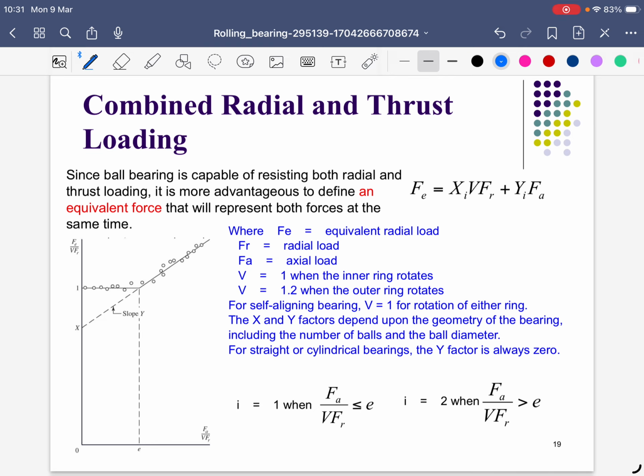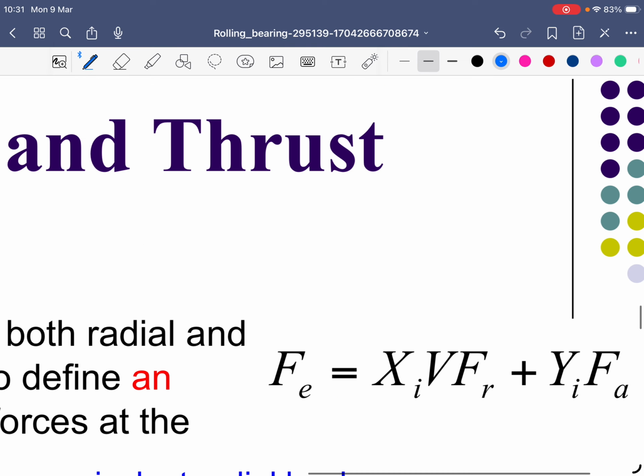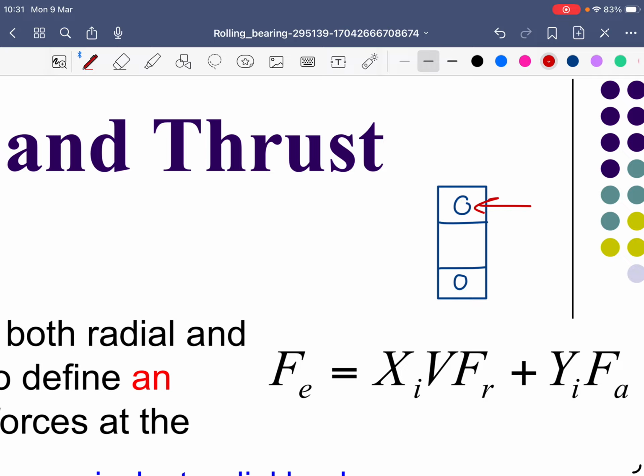This will support this vertical gear. You have the load only in one direction, like this. Okay? This is a spur gear. If you mean this shaft and you have the spur gear here, the load here is only in this direction. And then the load that is transferred to the bearing here is only in the radial direction.